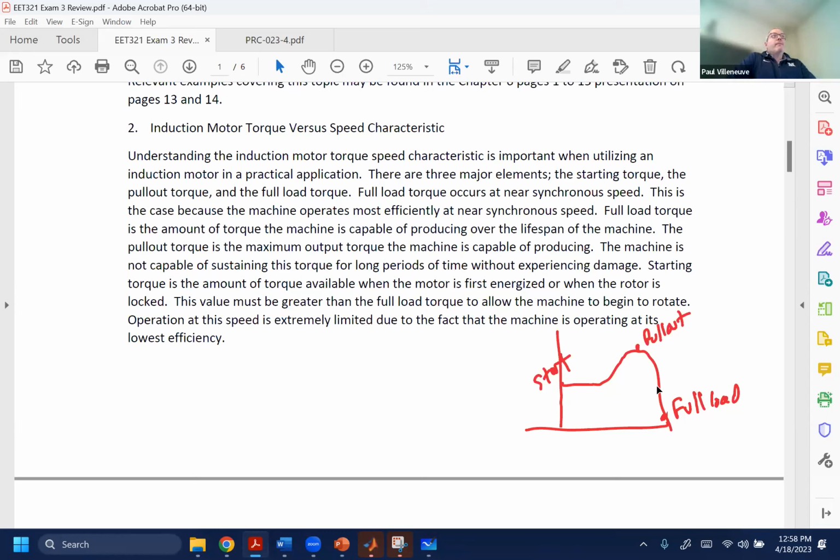Okay. Yes, sir. So from my experience, when you use shims for valve branches and stuff, you could also use them to level out the motor as well. Yeah, so normally what happens when you have a motor, right? You don't want to stick it right on the concrete floor. Usually you raise it up a couple inches, 3 inches, mainly because you don't want people walking into it. If water or something spills, you just want a little bit of clearance. I think they call it a housekeeping pad is the term that you would use. And why is it a housekeeping pad? Because if somebody's brooming along, you don't want them to just get stuff into the application. So you pour a housekeeping pad.